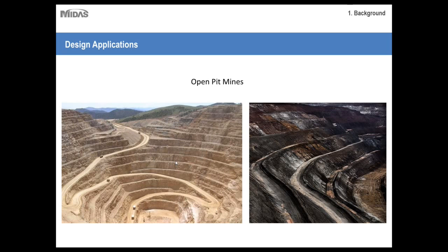Most walls of the pit are generally dug at an angle less than vertical to prevent and minimize damage and danger from rock falls. This depends on how weathered the rocks are and the type of rock, and also how many structural weaknesses occur within the rocks. Because typically these are excavated along rock lines or rock layers, there isn't too much need for structural supports.